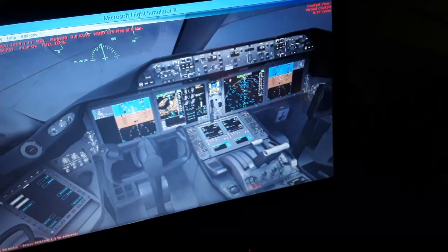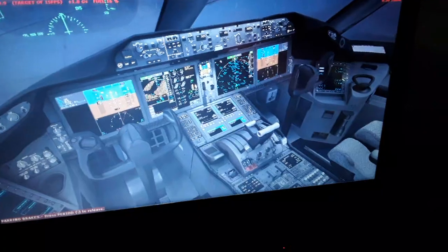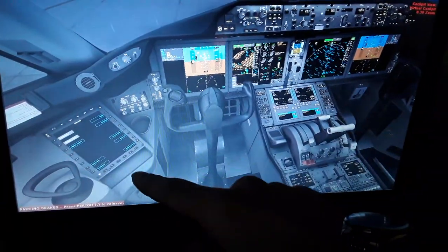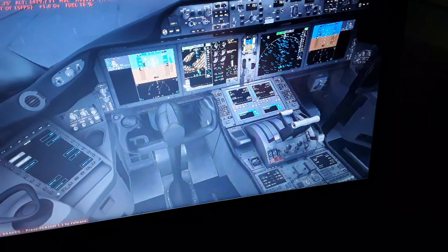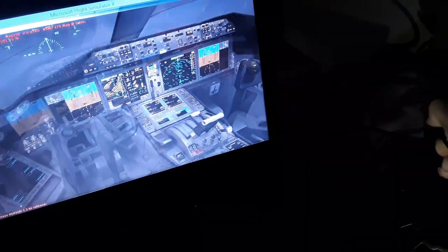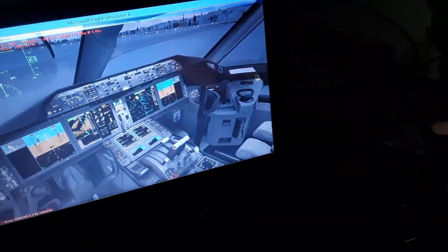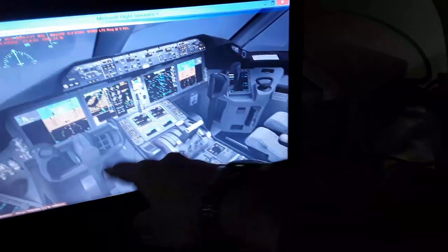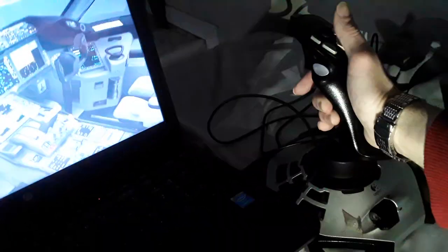So to control, the rudder pedals. You can see we have the tiller also just for the nose wheel, and the rudder pedals together, nose wheel and rudder on the ground, left and right turn. I have it in my joystick, both sides are interconnected, the captain and the first officer. In the Boeing also the yoke is interconnected, in the Airbus it's just the rudder pedals and the joystick inputs.